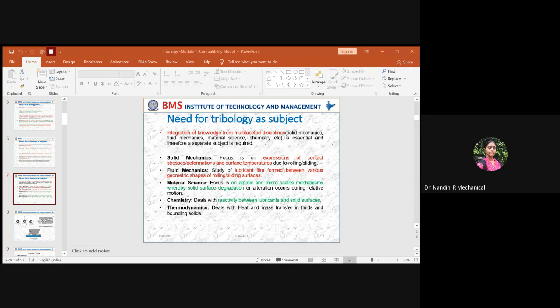Next is the journal bearing. You have abrasive wear resulting, and this is the rubbing wear, which is happening in a journal bearing. These are the two examples we are considering under journal bearing. The left-hand side is a photograph of a centrally grooved engine bearing.